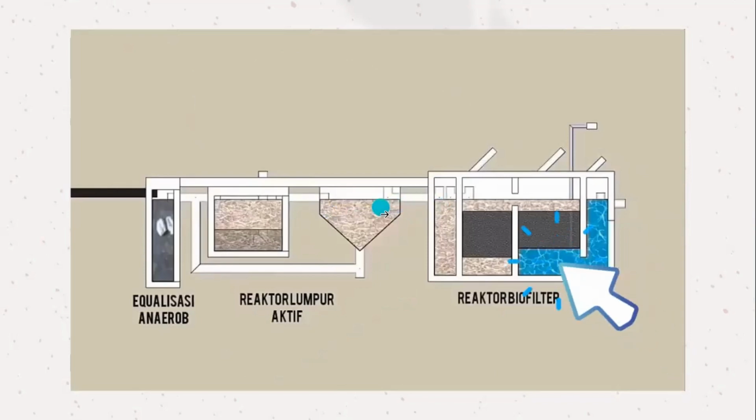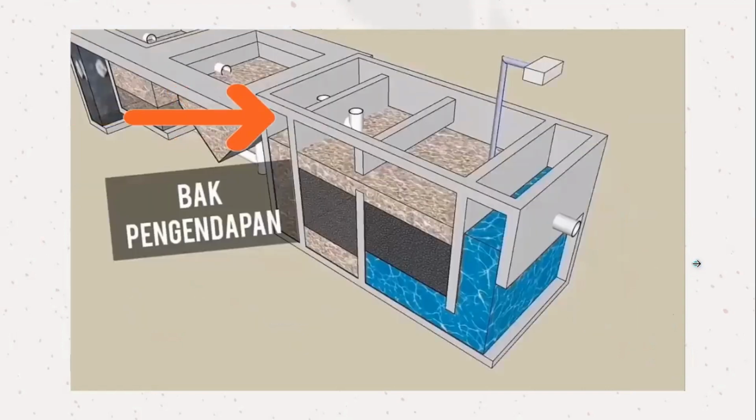The runoff water from the initial settling tank will then flow into the anaerobic biofilter reactor using the anaerobic and aerobic biofilter wastewater treatment process. Inside, the anaerobic biofilter reactor is filled with honeycomb-type plastic media. The anaerobic biofilter reactor consists of two chambers, namely the sedimentation basin and the settler bed.